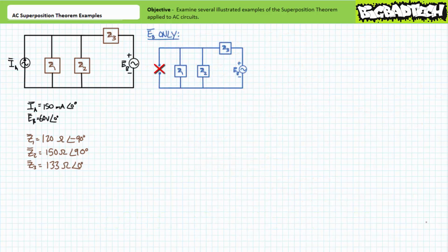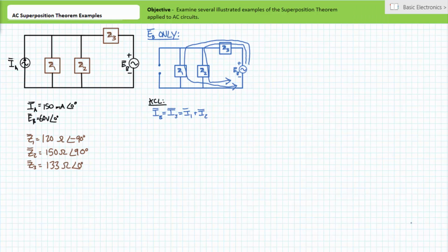Current source IA is removed from consideration by replacing it with an open or infinite impedance path. Again, the inclusion of this open has fundamentally altered the nature of the original circuit. A Kirchhoff's current law analysis illustrates that source current must travel through impedance element Z3.